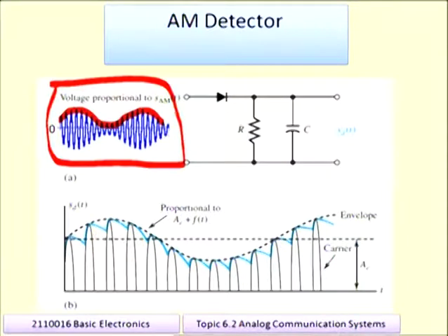So in that case we can use a diode, because the information is available in both envelopes. You can see that below also there is one envelope. So this is the positive side and this is the negative side. If you use a diode in this way, it will pass only positive cycles. If you reverse the polarity of the diode, it will pass the negative side. But for an audio signal, it is not much important because the human ear is not sensitive to the phase information.